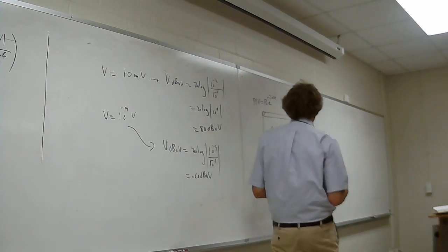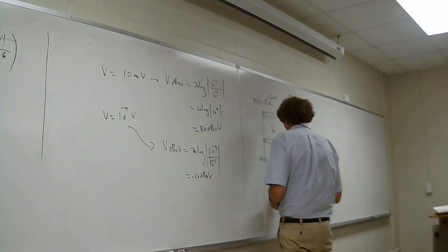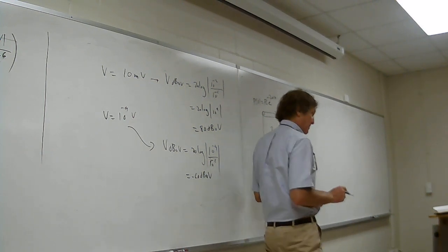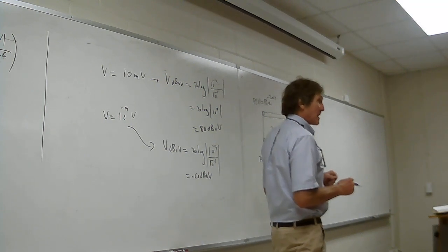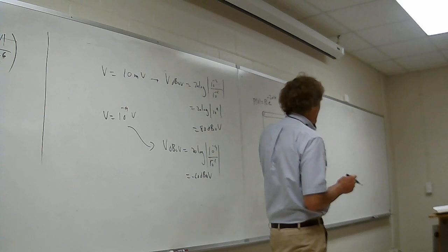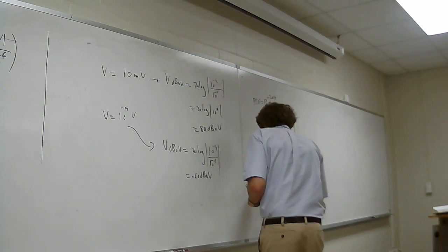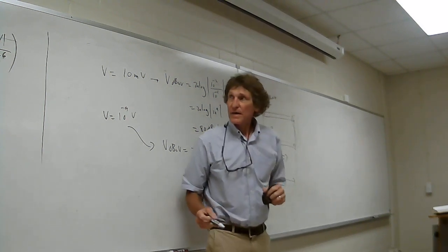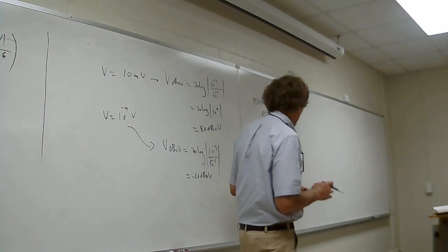So it's something that's traveling in that direction, assume the line's infinite. So how much power loss occurs over a 1 meter section? Now I want you to just take a look at this. If I have a 1 meter section here, what we're going to do is see the power loss in dB and also in Nepers per meter. So alpha right there has units of Nepers per meter as such, and that's the alpha that comes from that gamma is equal to alpha plus j beta.